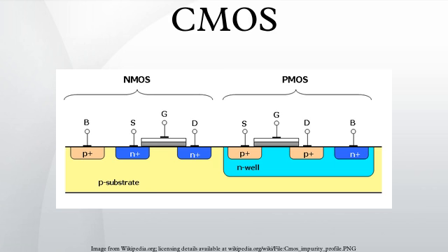Broadly classifying, power dissipation in CMOS circuits occurs because of two components: static dissipation, sub-threshold conduction when the transistors are off. Both NMOS and PMOS transistors have a gate source threshold voltage, below which the current through the device drops exponentially. Historically, CMOS designs operated at supply voltages much larger than their threshold voltages.